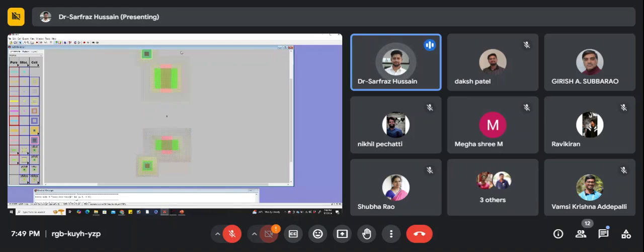So this well connection. Here we can connect the VDD and ground. In this case, let's say we want to connect the drain and gate, so we'll place it. Drain and source we need to connect, right? So here we'll place one, and another we'll place on this side. Similarly for the PMOS, we can use this P active. We'll place one here, and another somewhere here.